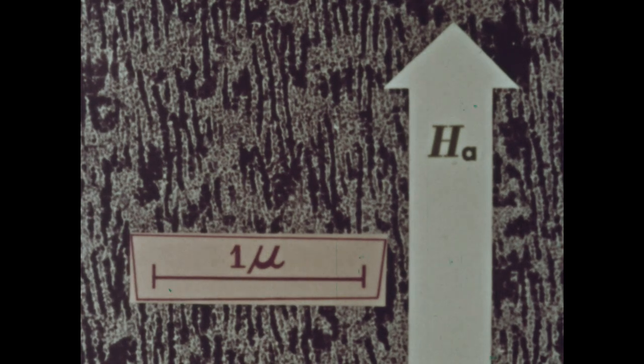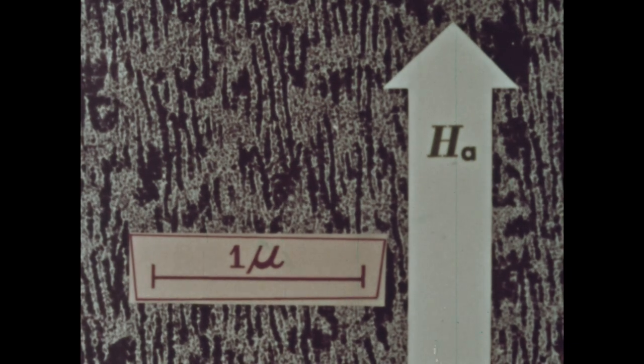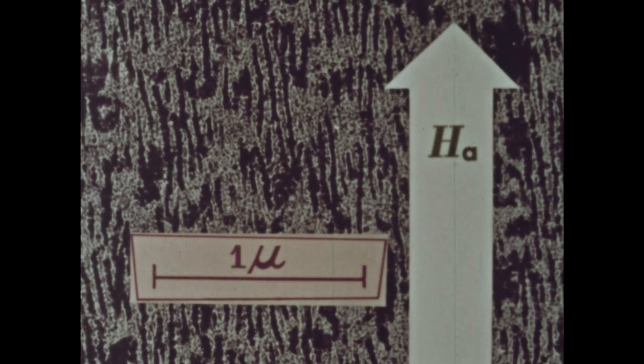Here is an electron micrograph which is representative of alnico 5. From study of such pictures, scientists now believe that alnico 5 is a non-magnetic matrix containing precipitated magnetic particles that have an elongated shape. In preparing the material, it is heat-treated in a magnetic field that is applied parallel to the direction in which the final magnet will be used. This treatment aligns the precipitated particles in the field direction and produces a significant increase in the magnetic quality of the alnico alloy.